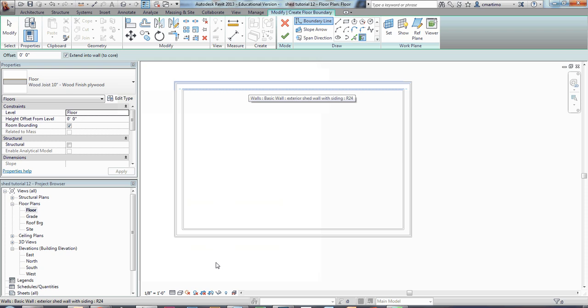So I can come hover over my wall here. I haven't clicked, I'm just hovering. I put my mouse there, and I'm going to hit the tab key. And when I hit the tab key, I'm going to get all 4 walls. It's going to say chain of walls or lines. After you've hit that tab key, if you move your mouse, you're going to deselect that. So again, you want to move your mouse. So you're just hovering, no click. I hit my tab key, and then I'm going to click, and you can see that selected all 4 of them, going all the way around for me, and kind of does some of that work. And so then I'm just going to say check to finish that.